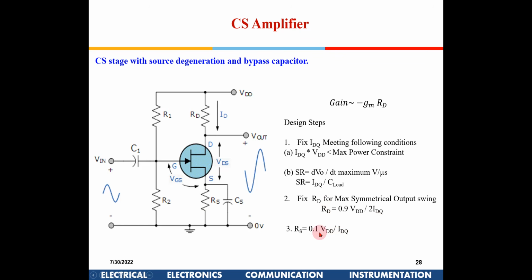So these are the two variations which come in. Now this combination of RS should be such that if my operating signal is 1 kilohertz, this RS should bypass even 100 hertz. If it is 1 megahertz, then 100 kilohertz. This RS combination should come like that. These R1 R2 in parallel in combination with this C should cater for, at least 1 decade, all these poles which are formed. So you have to decide the value of the capacitance accordingly, right?